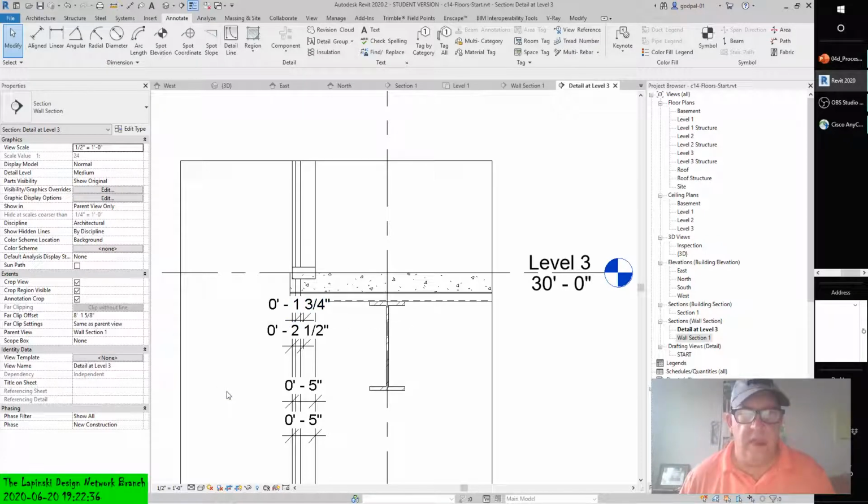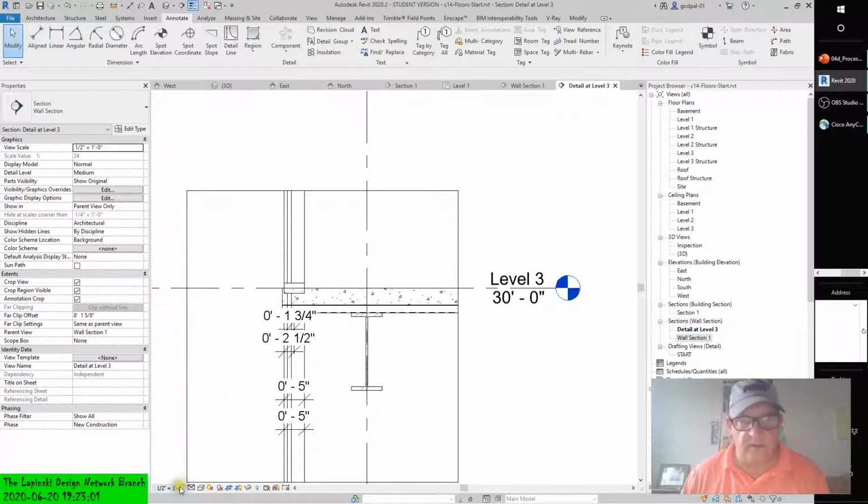Now, at a half-inch scale, which is 24, 1/8 inch scale, 1/8 inch text, you have to do the math. It's the golden ratio, right? If you're at 1/8 inch scale equals a foot, and you want to have your text at 1/8 inch on your paper, well, the text has to be 12 inches. And it's the same concept here.